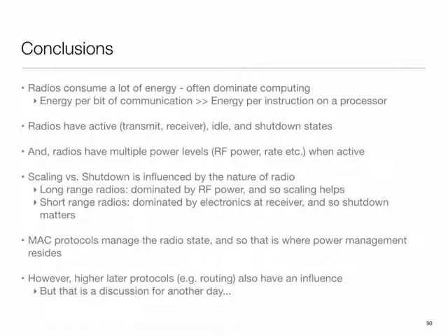So imagine if everyone had atomic clocks, and two nodes agreed they're going to exchange a packet at time t. They wake up at time t and they squirt the bits out, no preamble needed. Because we had high quality clocks, I can eliminate that. So in fact, motivated by this, the US DoD invested quite a bit in these chip scale atomic clocks. So the idea is that I can entirely eliminate the notion of preamble. I can have radios which basically just wake up and send the payload, no preamble needed, no synchronization needed and all, okay.